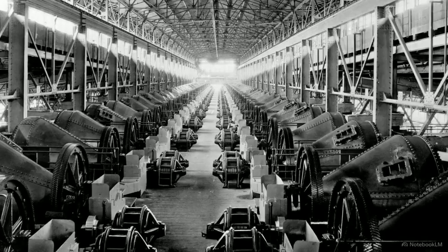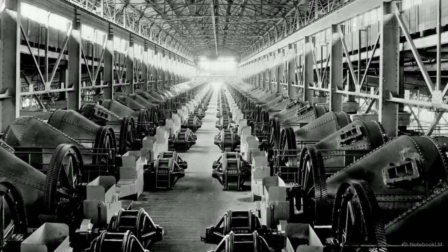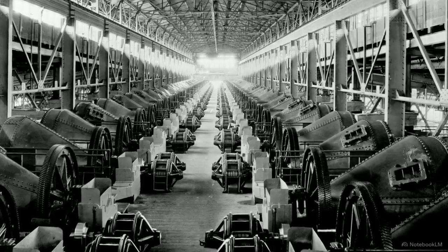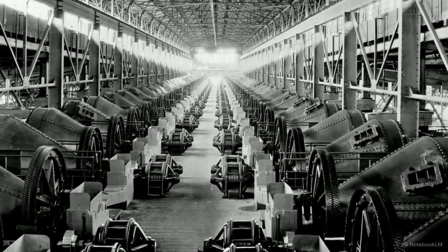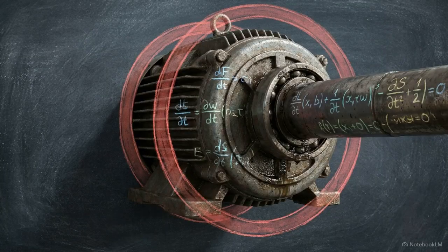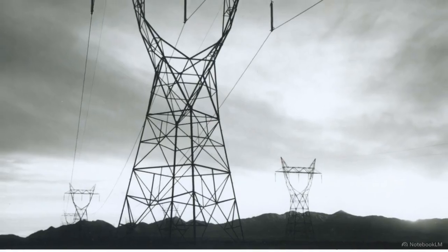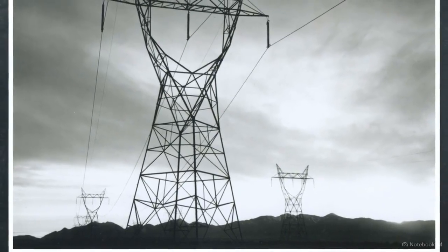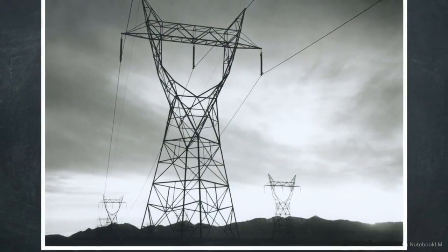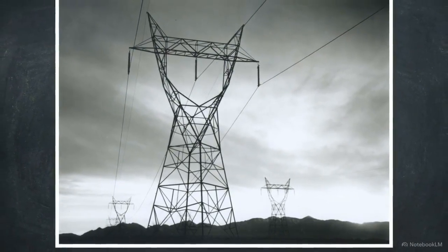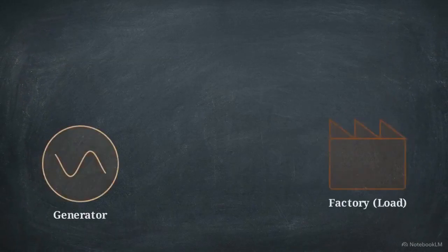Industrial environments, like manufacturing plants and pumping stations, are dominated by heavy machinery. Physically, these large electric motors are just massive inductors. To maintain the immense magnetic fields required to turn their drive shafts, these motors constantly pull a massive supply of reactive power from the grid. If the distant power plant supplies these VARs, this useless pulsating reactive current has to travel for miles across the physical high-voltage transmission network. This vector diagram maps the consequence.